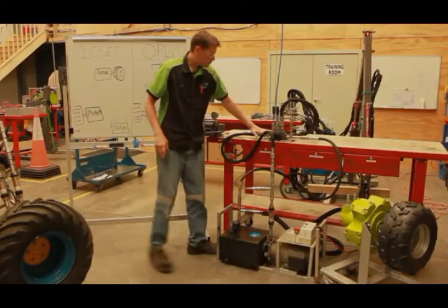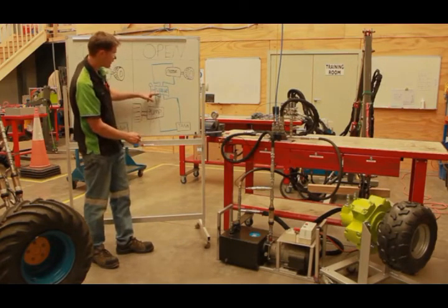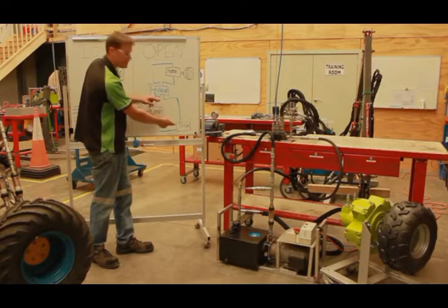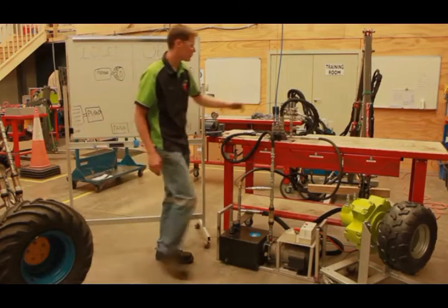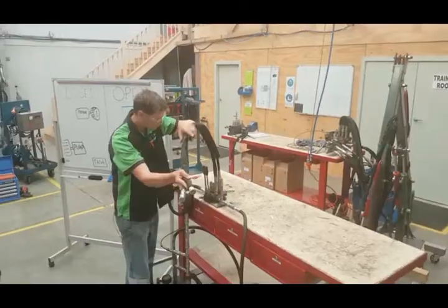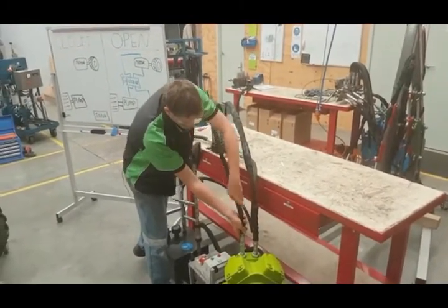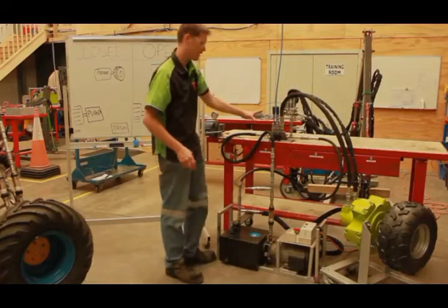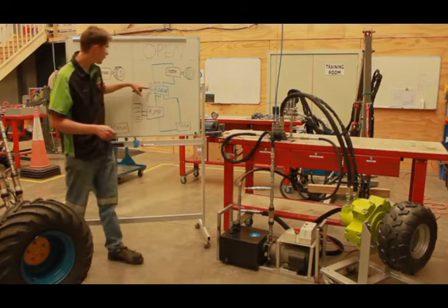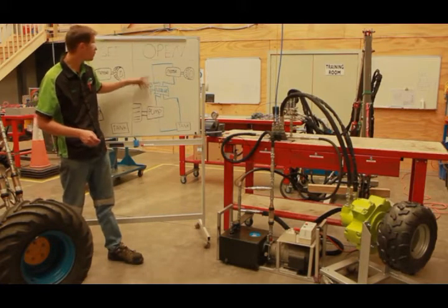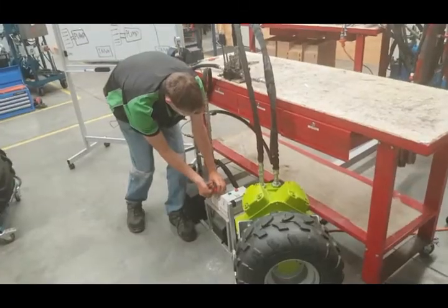And now with my directional control valve, I've connected these two hoses. From the pump is connected into the valve, and the return from the valve is connected to the tank. All I need to connect now are the top two hoses which go to the motor. And these are called our A and our B working lines when we talk about them in reference from the valve. And that's it. I've now connected my hydraulic directional control valve into my open loop system. I'll remove my isolation and we'll give a demonstration.